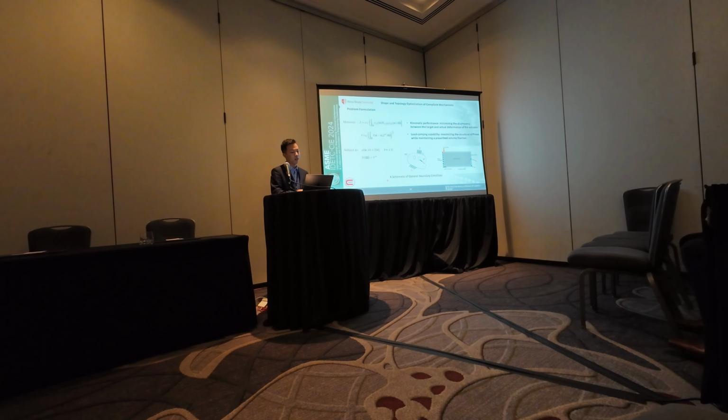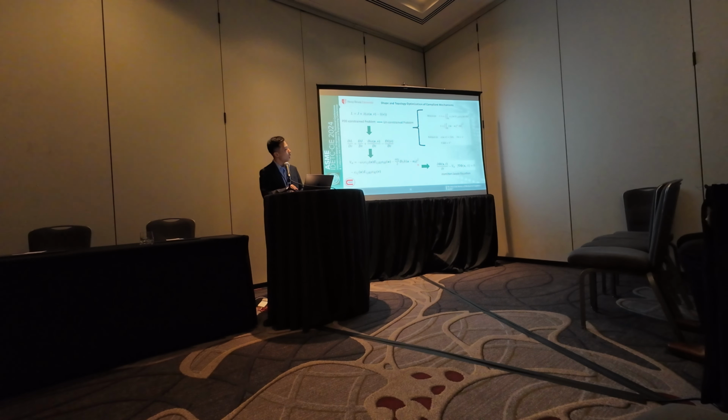So we can see here the schematic of the general boundary condition. This problem can be formulated as a PDE constrained problem, because we have the Dirichlet boundary condition, the Neumann boundary condition, and Vn, the design velocity acting on the boundary of the surface. Here we are going to use the Lagrange multiplier method, with which we can transfer the PDE constrained problem into an unconstrained problem. L is the Lagrange function, J is our objective function, a(u,v) minus l(v) is the governing equation, and we have the Lagrange multiplier.